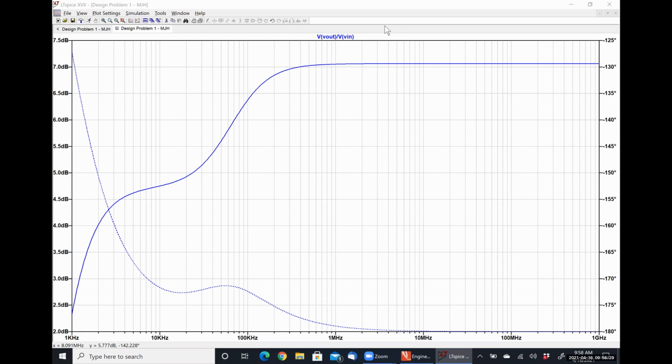So today is more of an exercise. You're 100% correct. You could iterate on it now that we know what the gain is and try to better estimate what our Miller resistances RFA and RFB will be. But when we get into actually analyzing the frequency response of transistor circuits, that's pointless because that feedback resistor doesn't exist. So did that illuminate things? Okay. All right.